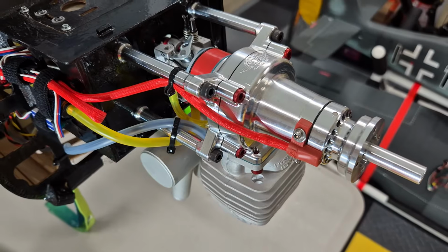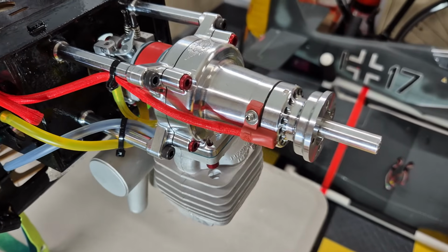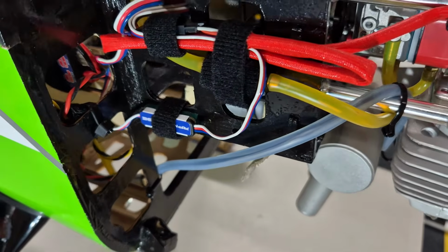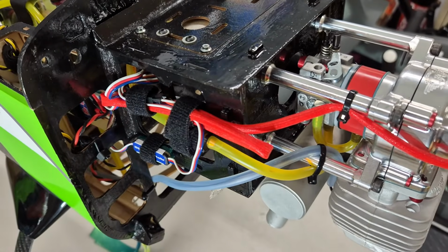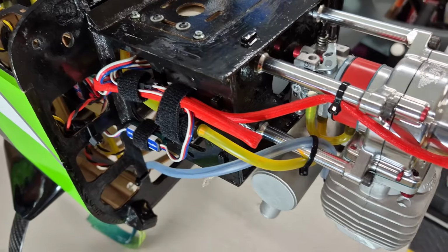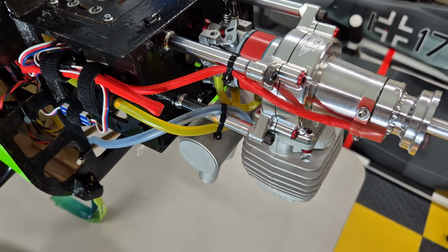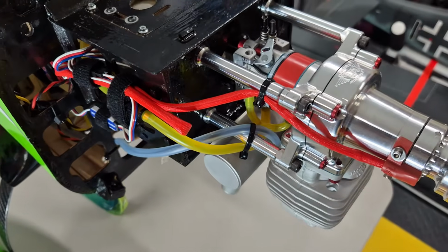So yeah, that's how we get the RPM from a petrol engine using an ignition system back to the core. Now the DA35 engines, because they use a Hall effect sensor in a special configuration, we are required to use the RPM probe. Some other motors have a tacho output or an RPM output, and you don't need to use the RPM probe. But in some instances like this, with the DA engines, you need to use the RPM probe to get your RPM signal before you feed it into the spark switch RS.